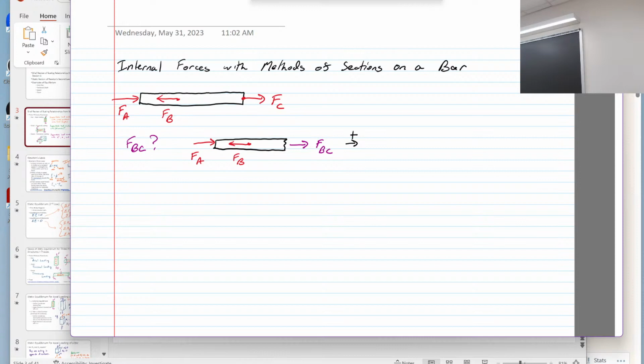We should do the same thing, we just see what these are. Is the negative important? Which one? So you're talking about this, right? This equation right here is just to show external equilibrium. When you're doing the internal equilibrium, you make the cut side positive. When you do that, this will end up being a minus moment, so it will be a minus moment, right?